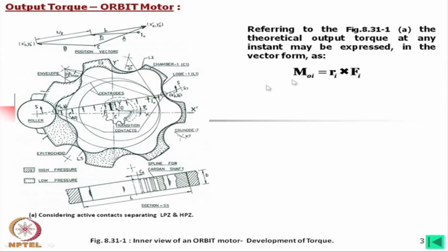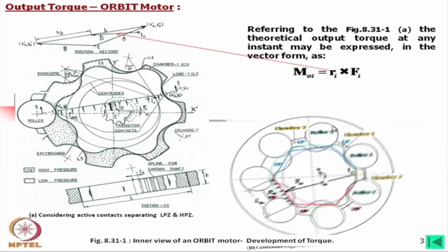So, that torque must be the output through this body, which is nothing but the star. So, we can write down this is the torque. Sometimes it is called the energy method, but whatever may be the name, in this way we can find out the theoretical torque output of this machine. This is the distance R_i, we should always remember.